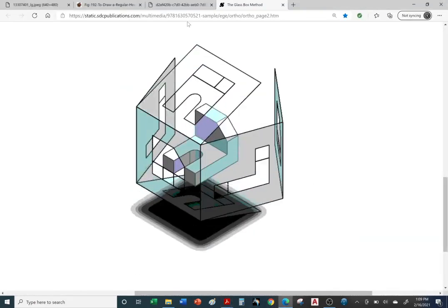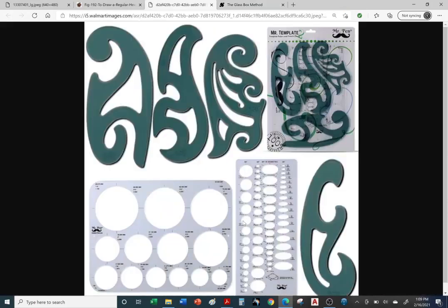So if we go back to the templates, if you were making a drawing of this drawing template, for example, all you need is one view, because if you look at it from the side, it's just a thin edge. So you would just draw one view and then call out the thickness of the material, whether it's 1/16 of an inch or 1/8 of an inch, for example. Okay, so something like this, one view is more than enough because it's a flat piece.